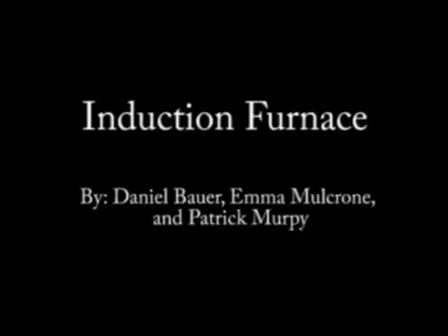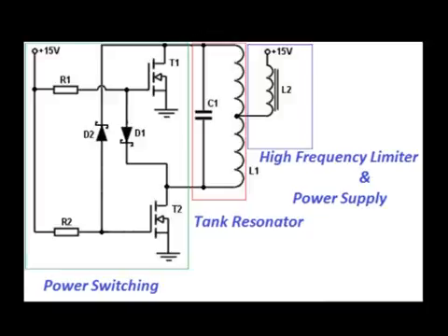I'm Patrick Murphy, and for our 201 final project, we built an induction furnace. The intent behind the induction furnace is to be able to heat up conductive or permanently magnetic materials. Our style of induction furnace is comprised of three different subsystems: the power switching, the tank resonator, and the power supply and high frequency limiter.